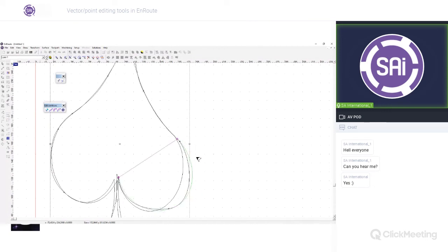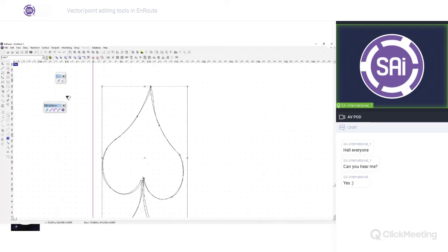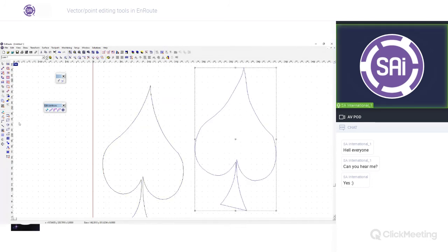So here, you can just drag these down, move these points here, to generate our original shape. If you have something that almost resembles your original part, what you can then simply do is, through the edit points, select certain points and it will still give you those handles to do the final touches.